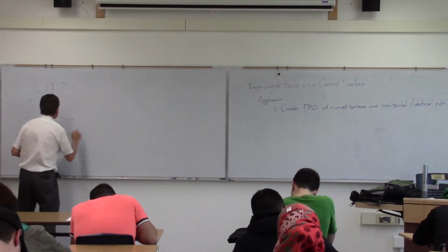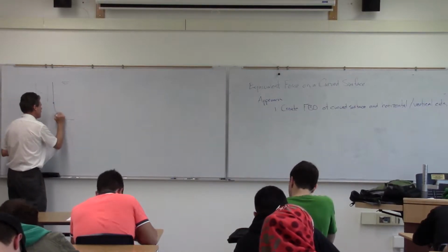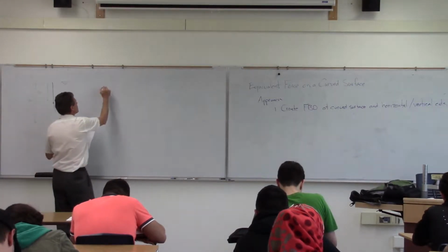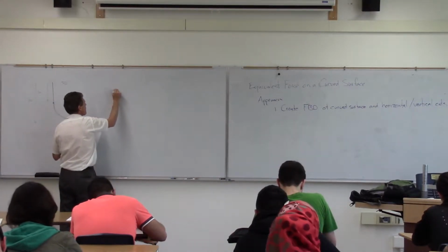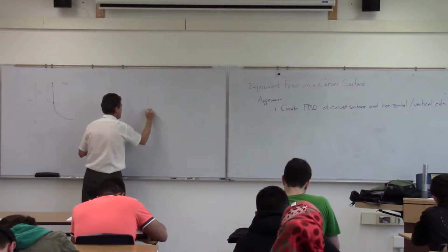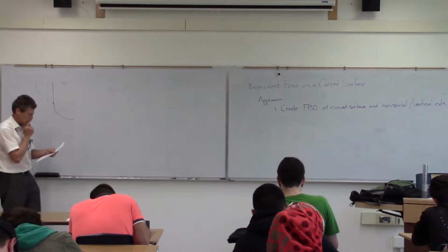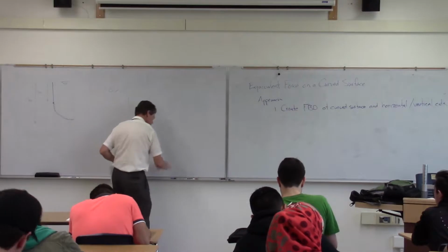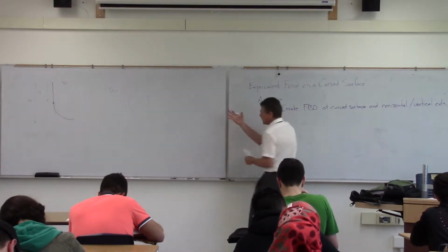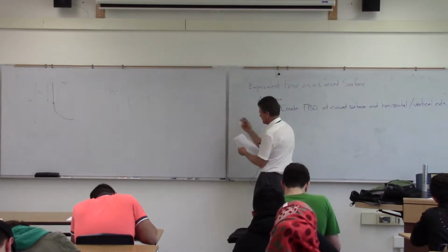So what we're going to do is cut that portion of the water out. So my free body diagram of that portion of water looks like that. Okay, second step. So we're going to create a free body diagram. We've cut that out, basically. We've cut it away from that gate there, and we're going to look at what that water is doing to that gate.